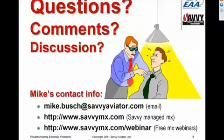Every charging system has some way of turning off the alternator. Usually it's a field switch. Sometimes it's a separate switch. Sometimes it's a switch that's combined with the battery master switch, either as a split switch, or in some of the real older airplanes, it's a single switch that turns them both on and off at the same time, which isn't a real great design, but some of the early airplanes did it that way.